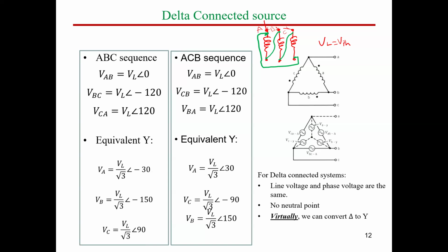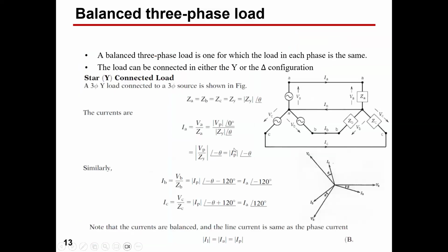So this is just the requirement. If you have delta connection, you would convert delta to Y in order to get the voltage magnitudes. Most of the time, we will not take care of the angles. Only in transformers we may calculate the angle to determine what's called the group number of the transformer, and we will discuss this later on. So this is the delta connection.